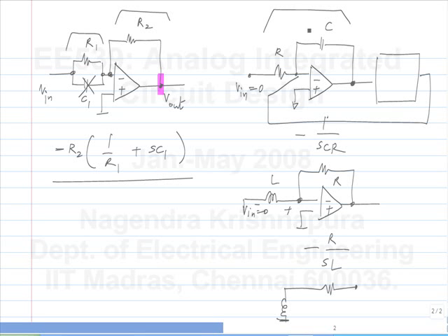So the only way to do it is perhaps to approximate it by having a very large resistor which provides DC negative feedback but perhaps can be neglected for the signal picture. So you can evaluate in more complicated circuits whether there is negative feedback or not, and it has to have negative feedback, otherwise it doesn't work. I mean DC negative feedback. This is true for every circuit. Afterwards we will make our circuits using transistors and so on. So every transistor has to get biased, which means that there has to be overall DC negative feedback around a high gain circuit like this.